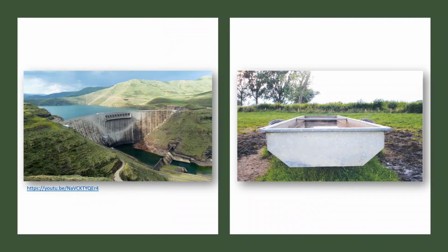The topic that you are going to learn about today is very important when it comes to design of hydraulic structures such as tanks or dams. Have you ever noticed that there are different shapes of dams? Have you ever asked yourself why? Or have you ever noticed that the thickness of the dam at the bottom over here is higher or thicker than the thickness over here? And have you ever asked yourself why? Now you should have a good idea. You should, in your mind, think that this is due to pressure, right? Because as you go deeper, the pressure gets higher.